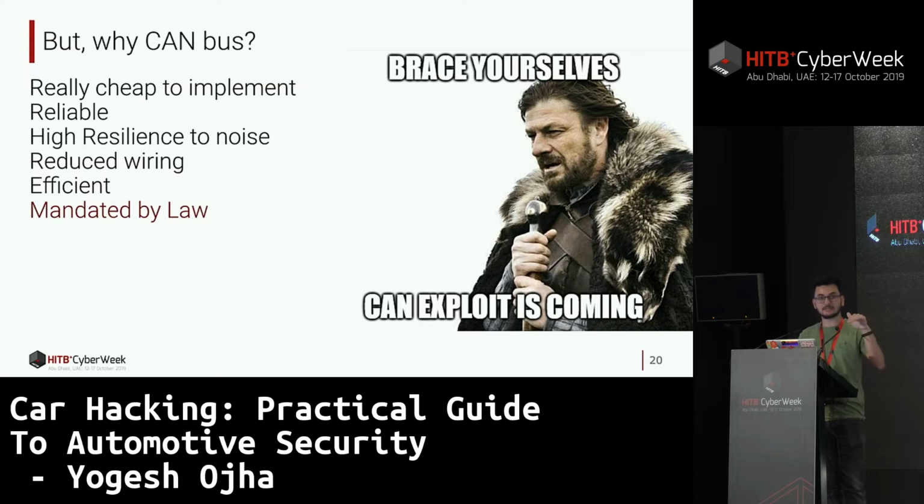So when the voltage is sent, it drops the same amount of voltage on one line and increases on the other line, either in the CAN high or the CAN low. This is what makes it tolerant to noise. One of the reasons CAN is efficient is because CAN packets are normally prioritized through an identifier in such a way that those with the highest priority are not interrupted.